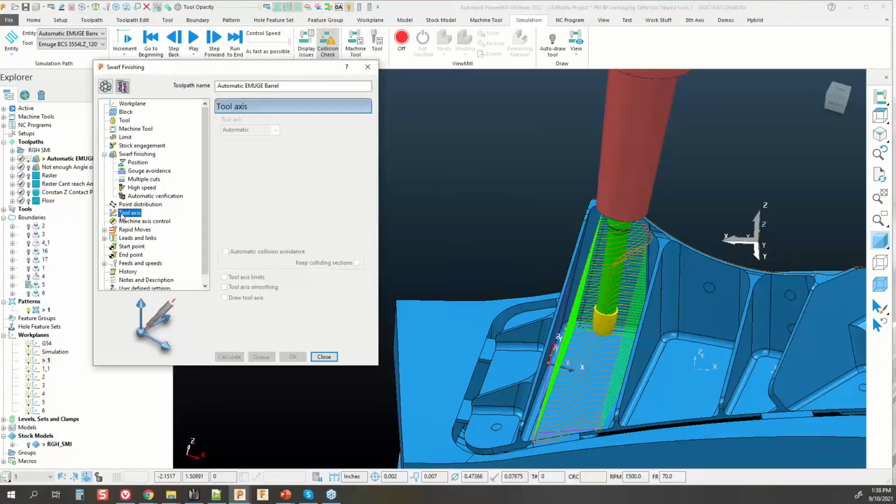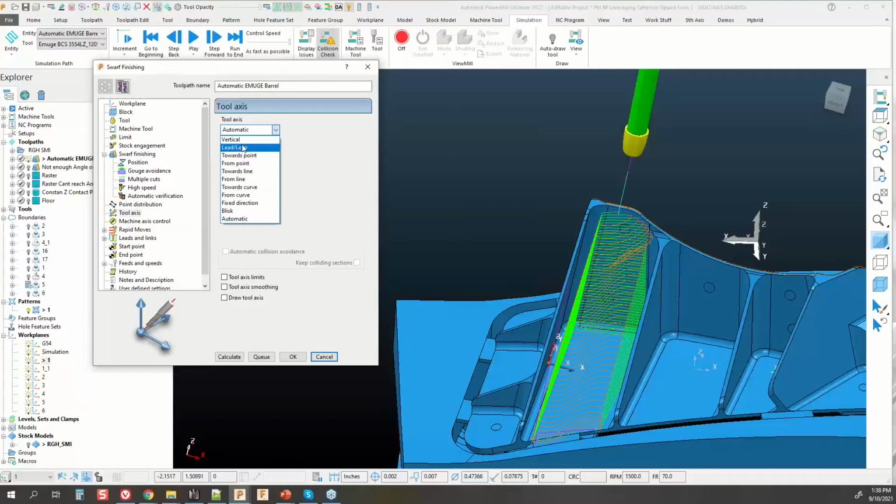However, what I actually want to be able to do is alter the tool axis and force the lean based on the average. And again, with Swarf, it only gives us one option. It's not allowing us to control the contact point of the tool to the surface like we would typically see with all the other toolpaths. All the 3D toolpaths allow us to contact with the tip of the tool based on either contact, normal, or vertical, or a few other options depending on the toolpath. But in this case, it was always forcing the along of this tool along the shank.